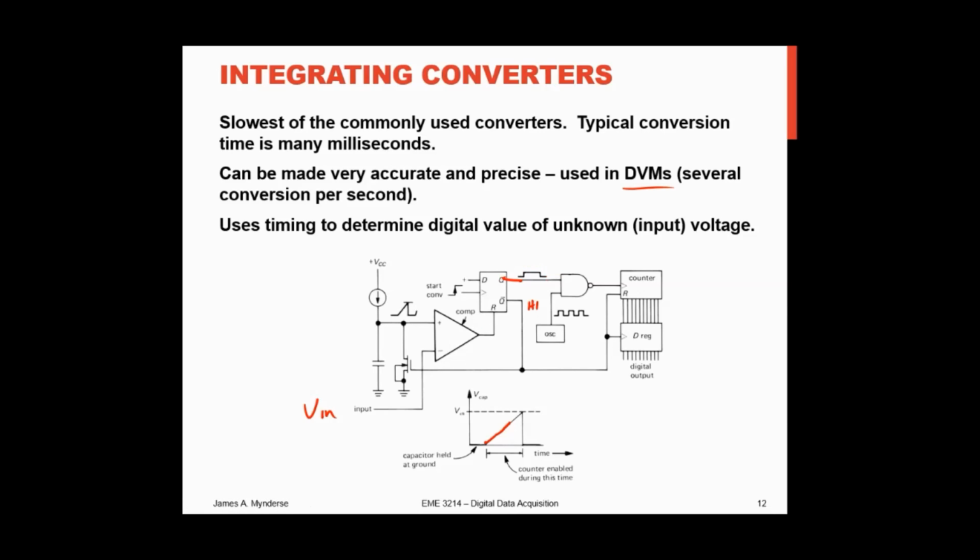If I took that pulse, and this is happening all the while we're doing everything else, and I have this oscillator here, which is just giving me an on-off, and I do a NOT and an AND, so that with these two signals, what I end up with out here is, instead of just one pulse like this, or a number of pulses like that, I end up with some number of pulses that correspond to the oscillator frequency and the duration of this pulse, which goes back to the amount of time it took to charge that capacitor, okay?